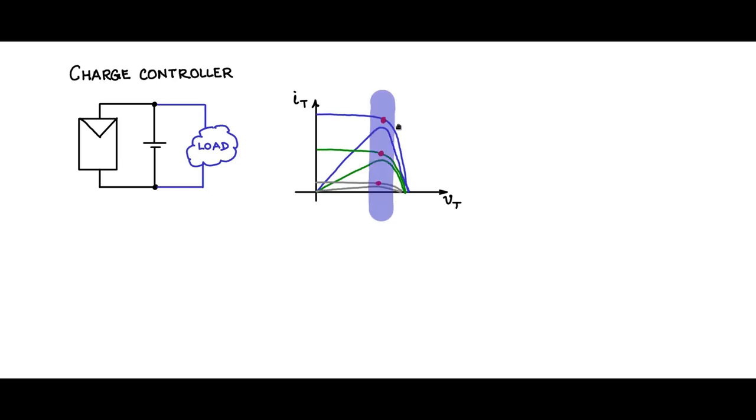So if I draw a band like this, this band would be the zone of operation for peak power point or maximum power point, where in this region of operating point you will be near MPPT, and that is sufficient for most of the applications because of a slight flatness in the hill of the power versus V curve.